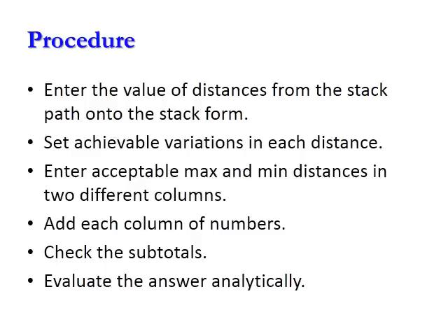Now the procedure. Enter the value of distances from the stack path into the stack form. Set achievable variations in each distance. Enter acceptable maximum and minimum distances in two different columns. Add each column of numbers. Check the subtotals. Evaluate the answer analytically.